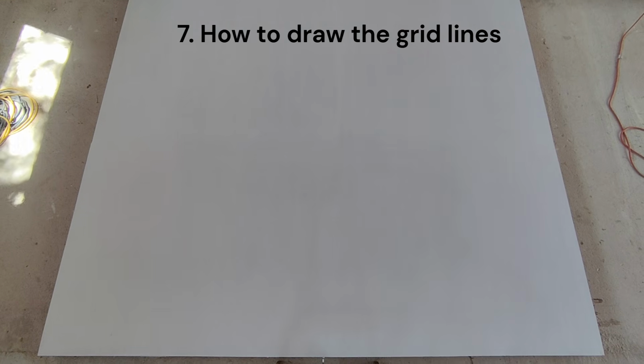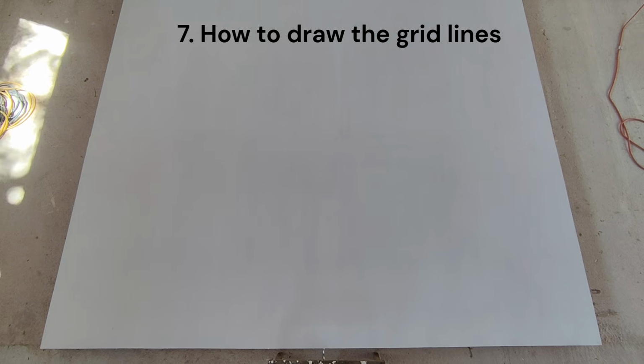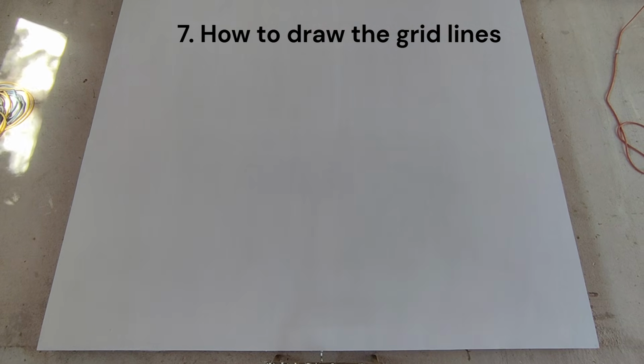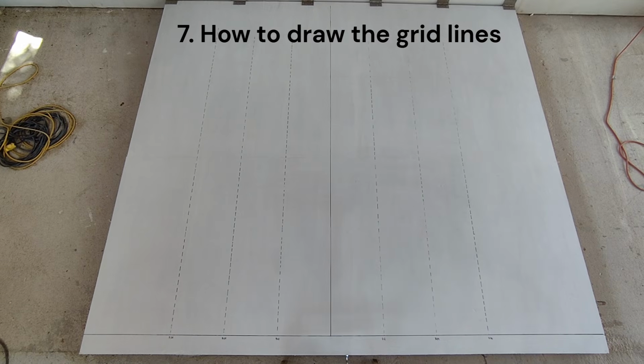7. How to draw the grid lines. Let's assume you have a 3 by 3 meter lofting table, or maybe you have a full-size lofting table with a part for the body plan. Now it's time to draw the grid system.